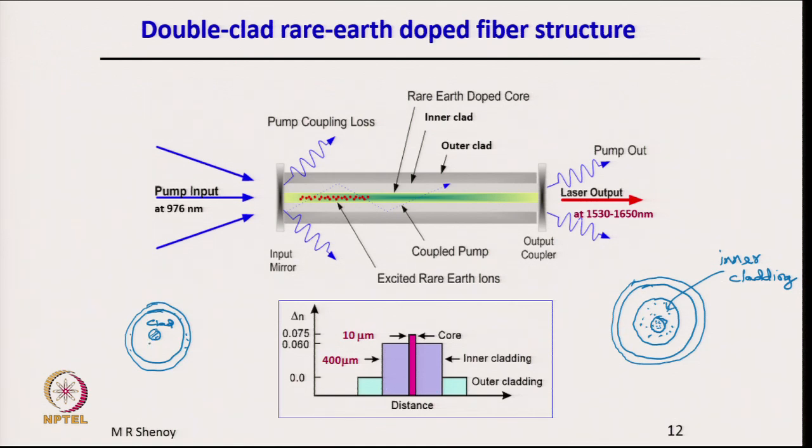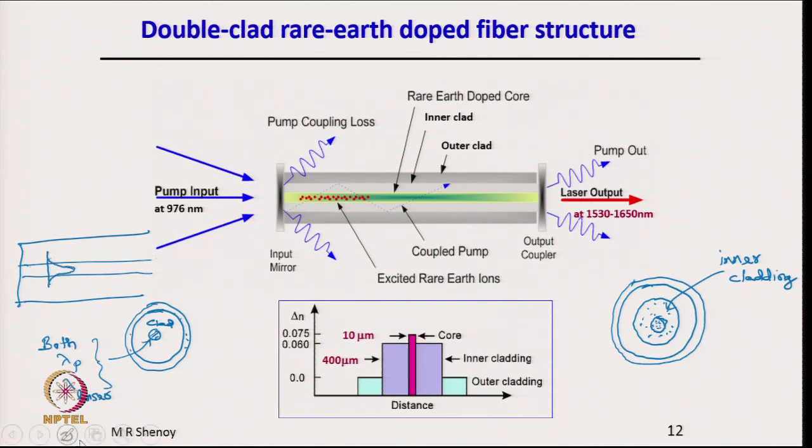If we put, as in the normal laser, both lambda p, the pump, and lambda s, the laser wavelength, in the same core, both are in the core, and therefore, if I show a transverse picture here of the fiber core, then the pump has a field distribution which is like this, and let me show the signal with a different color, and the signal has a field distribution which is, because it is at a longer wavelength, more spread, but the two field distributions overlap.